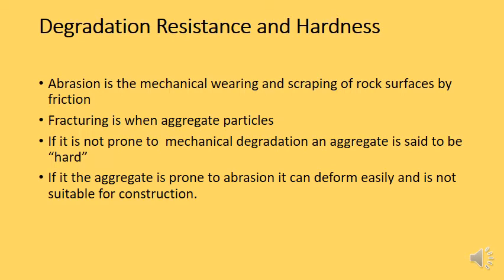So maybe you've noticed this driving around certain roads in Kurdistan. Occasionally the road, especially where the tyres of the car are driving, after a while, if the road is kind of old, it will go kind of smooth. It will be a smooth surface just where the tyres are constantly driving on it. And that's basically the aggregates inside the tar seal, the road surface, wearing down. They're being smoothed flat. And basically, eventually the road will wear out, it will get cracks in it, and you have to remake it.